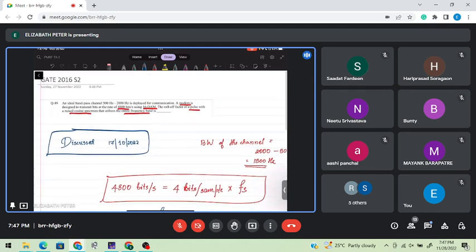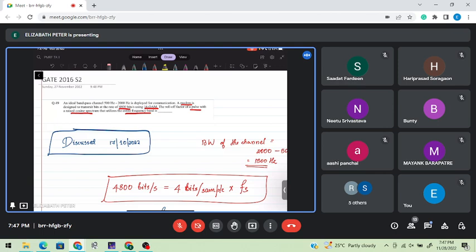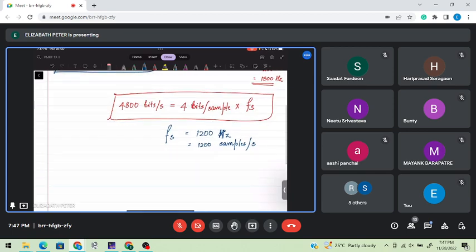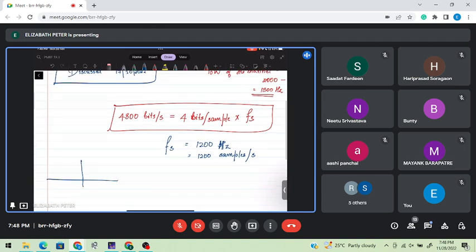Now, we are asked to find the roll-off factor of a pulse with a raised cosine spectrum that utilizes the entire frequency band. Today we have seen so many questions that use various pulse shapes, right? So this question uses a raised cosine spectrum. The raised cosine spectrum looks something of this form, okay? And this is given as (1 minus alpha) fs by 2, where fs is the sampling frequency, and this end is given as (1 plus alpha) fs by 2.